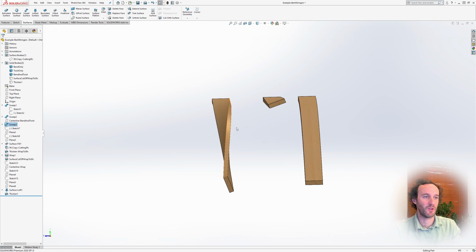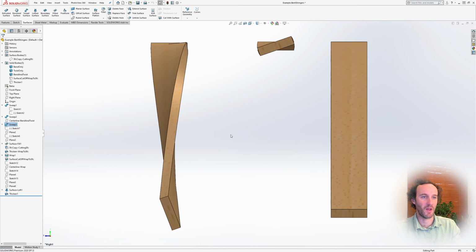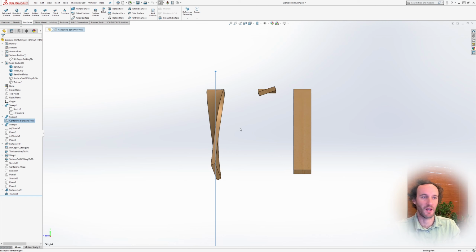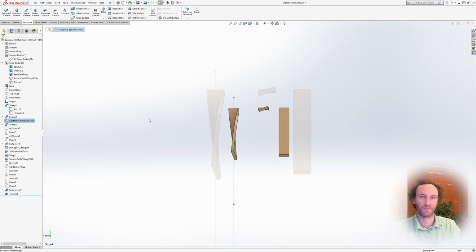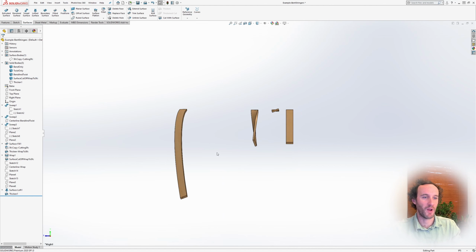So even though this one only has 20 degrees, if we put just 20 degrees in here and then bend it, a little bit of that bending is taking place along its harder to bend direction, that 1/2 inch direction. And so here you can see this sweep is forcing the center line to be constant. That's in contrast to a wrapped stringer.